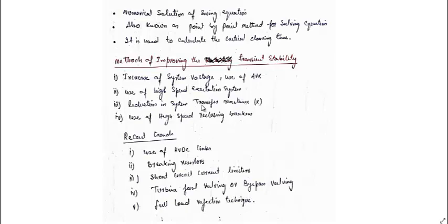Reducing the system transfer reactance, again the same reason, it results in the increase in the Pmax and hence the area.